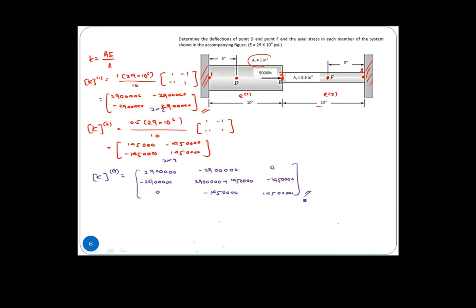Then we can apply our boundary. So here, of course, our displacements, I mean, talking about 3 times 3, then we have our K U equals to F, right? So this is 3 times 3, 3 times 1, 3 times 1. So our U itself is U1, U2, U3.